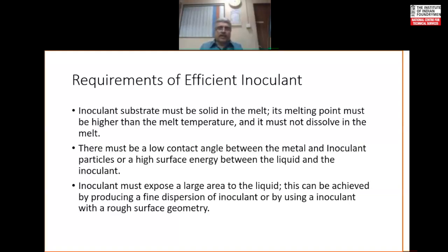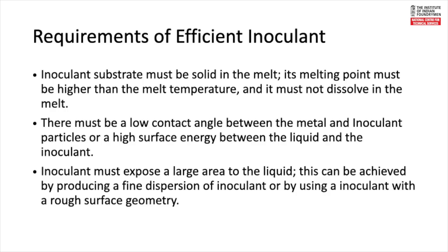This means you need a good dispersion of inoculating particles in the bath, or by using an inoculant which has got inherently rough surface geometry. There is an interesting point on this geometry of the inoculants, which I may, if we get the time, discuss later. This is in connection with inoculants which are used at the very last possible moment in the stream of the metal. But if time permits, I'll talk on that.